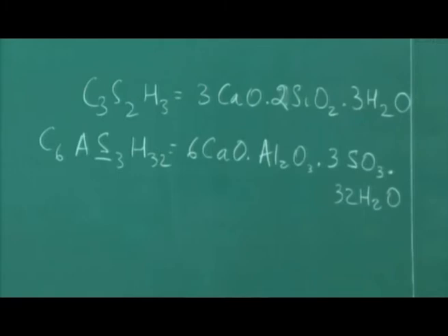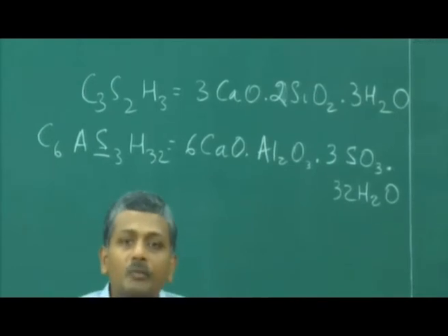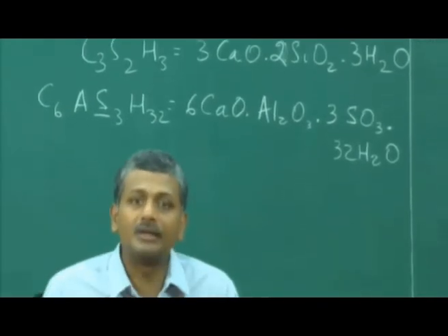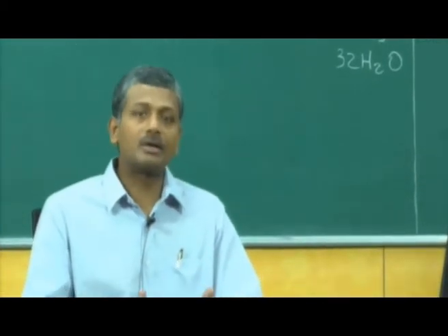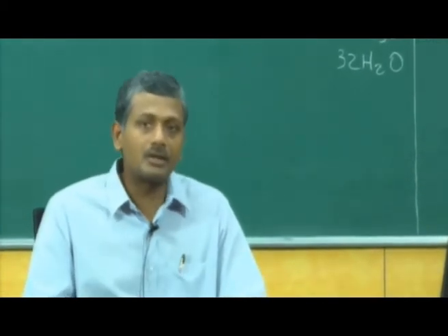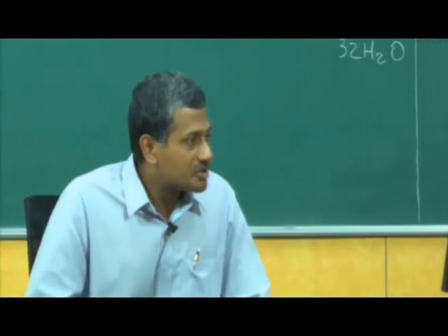Okay, that's your ettringite. And ettringite formation in fresh concrete is not really a problem, but when ettringite forms in hardened concrete, it is associated with an expansion which creates cracking in hardened concrete. That is what happens in the case of external sulfate attack. Now some people have asked some questions in the chat window also.